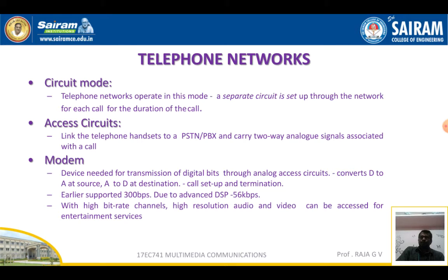And we have access circuits that link the telephone handset to the PSTN or PBX, which were designed to carry a two-way analog signal associated with the call. The PSTN and all the switches and transmission circuits that interconnect them operate in digital mode to carry the digital signal, a stream of binary ones and zeros, over the analog access, which requires a special device we call a modem.